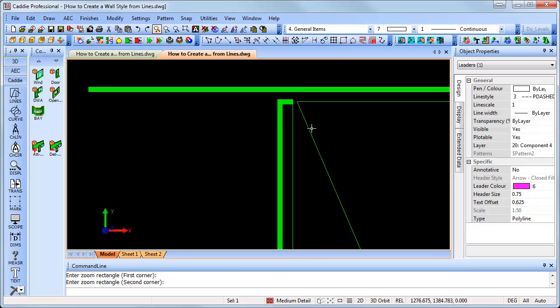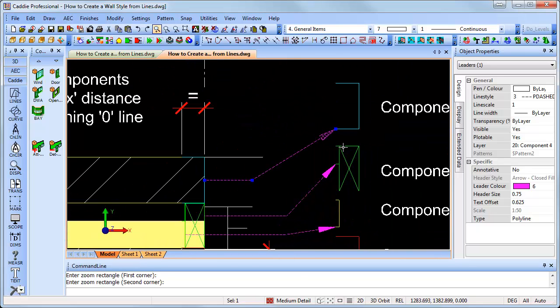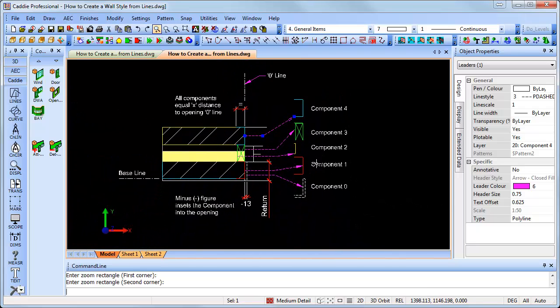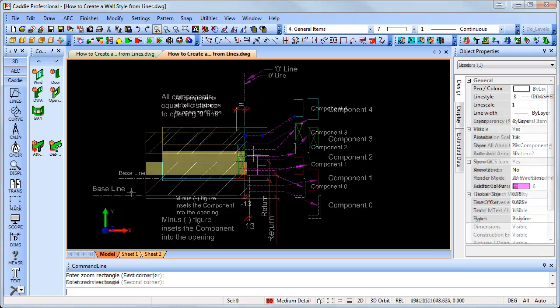Different thicknesses: 0 will actually show in the finished drawing, anything other than 0 will not show, but will still go to define our end cap. So taking a look at what we have here, we have a series of polylines which are drawn anti-clockwise, which define how we want each component to work.